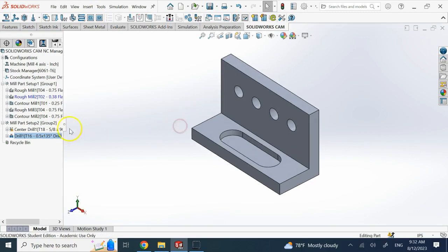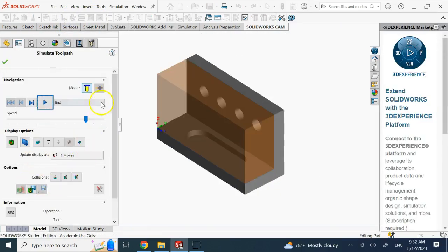But you clearly saw that at the end of it, when it did everything, so far the tool was going down. Now at the end, the tool was going left to right, and that was only possible because this is done with the 4-axis mill, where the tool can basically go in different directions. Now the correct thing to do really is to rotate this part, and then the tool again goes up and down. So this animation is not really showing what is being done in the machine.